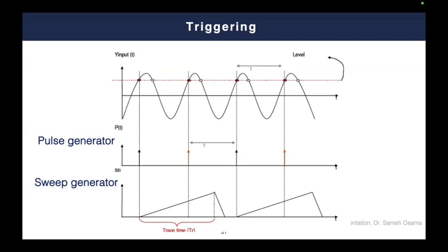However, the internal triggering mode is not capable of determining the real starting point of the signal, because simply it is related to the point at which the threshold voltage, this one in red, hits or intersects your sinusoidal signal, which is obviously not the real start point of the signal. That makes us reach a conclusion that in an oscilloscope, we are not capable of determining the real phase of a signal as far as we are using the internal triggering.